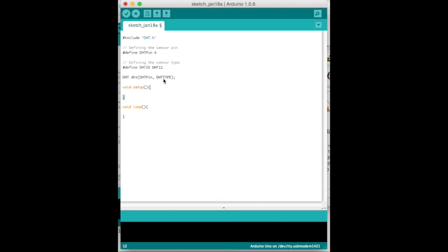Like we did before in our serial communication class, let's start the serial communication at a baud rate of 9600. Awesome. To initialize the sensor, we have to do a dht.begin. Okay, seems that everything is ready.